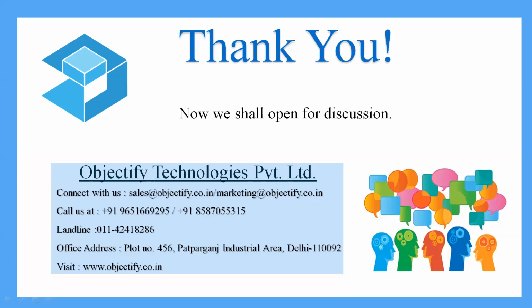There are very robust algorithms written for stereolithography triangle files, and it can go for very fine accuracies as well, up to sub-micron level, but the file sizes will become very heavy. So the standard practice in the industry, we use 10 micron as accuracy for a layer thickness of up to 50 micron, let us say. So I think I answered for the STL file preciseness.